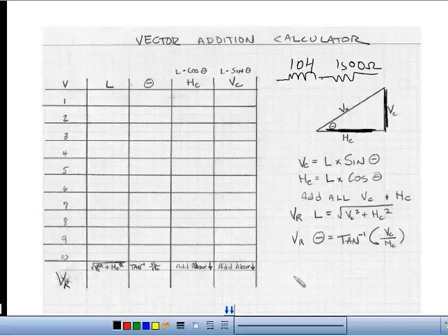So X sub L equals 2 pi FL. Substitute what you know, which is 2 times pi times 60 times 10. You'll get something like 3768. It's a little more than twice this 1500, so my drawing here is not really to scale.